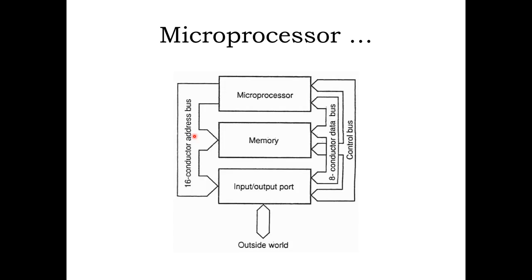How do I know how many numbers I can write? Any guess? When you have 4 bits, you can write 16 numbers, right? It's very simple. Just use 2 to the power 4. When you have 8 bits, you can write 2 to the power 8, which is 256. With 4 bits, you can only write 16 numbers, 0 to 15. If somebody gives you 4 bits and asks how many numbers you can write, you can directly tell from 2 to the power 4.